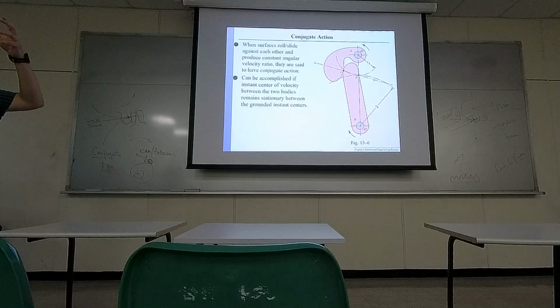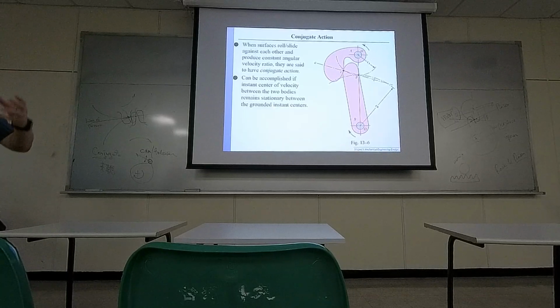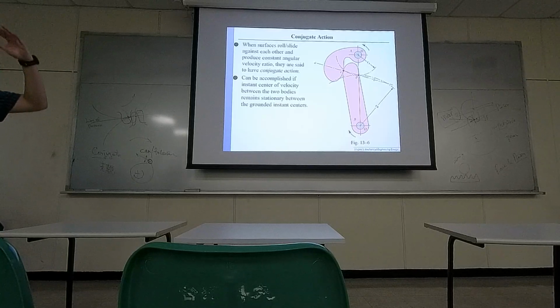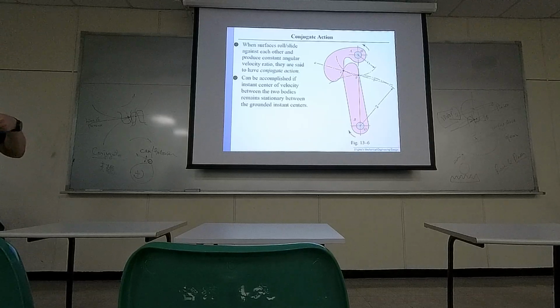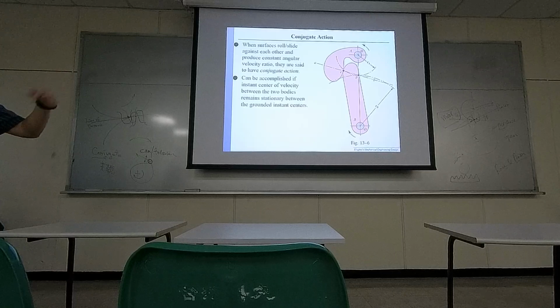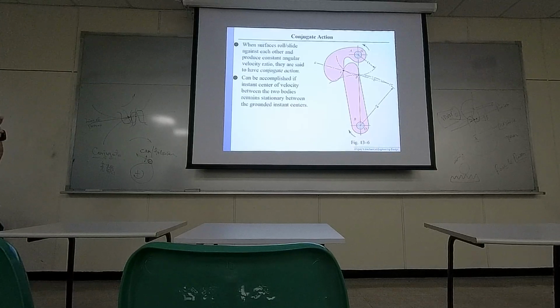But the piston only has this motion for pressurizing the gas inside the chamber. It doesn't provide the inlet and outlet of the gas. So you need to have valves opening, allowing gasoline coming into the chamber, close the valve, and then ignite to have explosion. After explosion, you will have the waste gas. You need to dump it to the outlet.